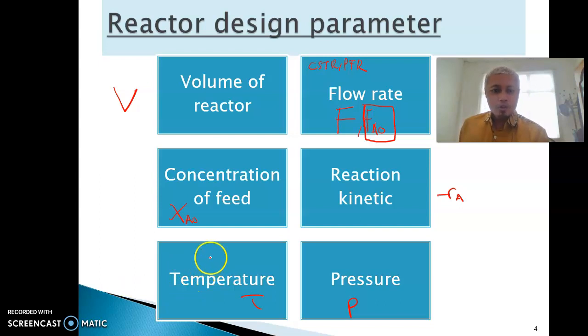We need to control the temperature. Normally the temperature is 0 degrees C, and then it can go up to 15 degrees C, depending on the catalyst or promoter that we use. If we have a promoter, we might be able to use temperature up to 15 degrees C. If not, we need to use 0 degrees C.